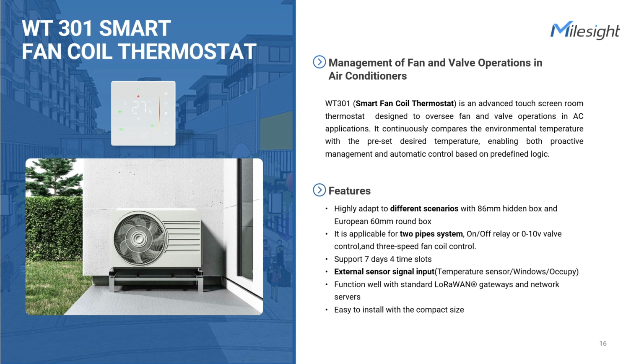And the third product is the WT300, an advanced touchscreen room thermostat. You can access parameters such as system mode, fan mode, and temperature set points. Valves and auxiliary electric heaters can be controlled using a relay or a contactor system switch controlled by the thermostat. What I want to emphasize is that it works with either a 0 to 10 voltage proportional integral valve or a 2-wire on-off motorized valve. Moreover, as it is equipped with an external NTC sensor signal input and keycard switch, you can link it with hotel room cards to control device systems, triggering specific schedules tailored to the hospitality environment.